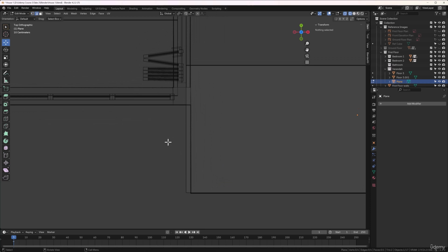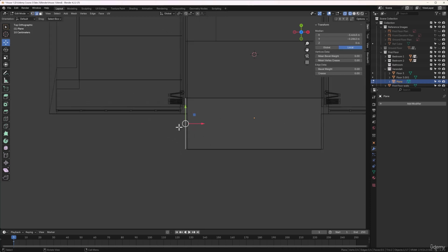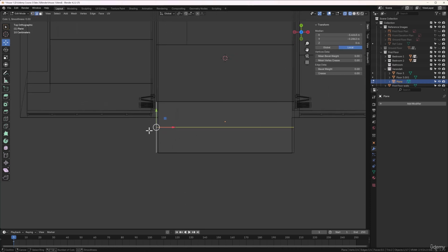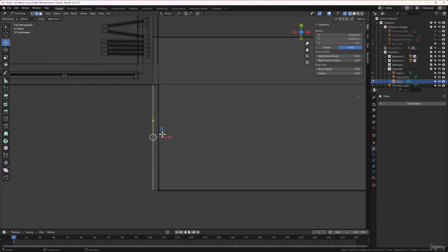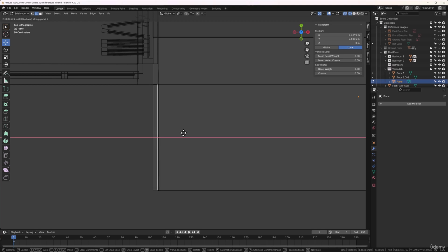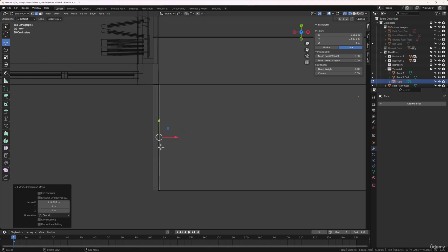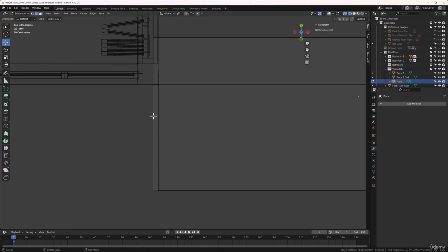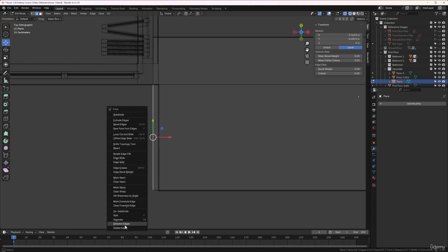Okay, let's press 2, grab this edge here, and let's press Ctrl R, and let's bring a loop forward like this. There we go, that's cool. Now that we've done that, let's grab this edge here like this, and press E and X, and bring this back until it's just shy of the edge of the veranda. Now grab this other one here, right click and dissolve that edge.